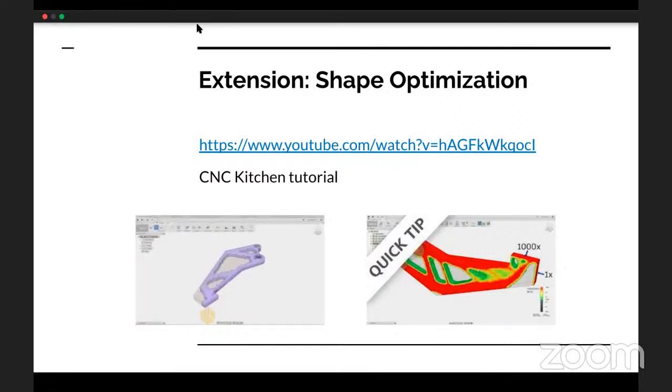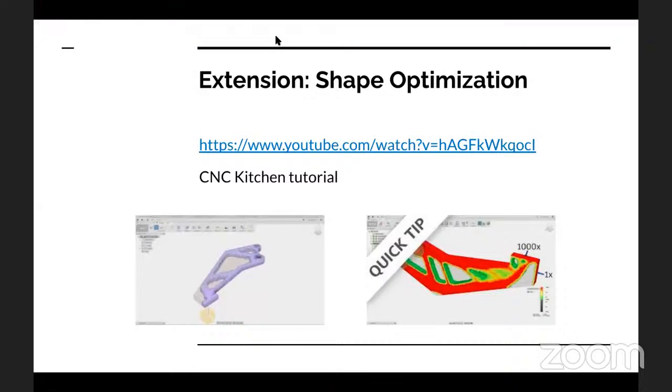So with this last part, it basically can take away unnecessary material, so it doesn't take as long to print, or it's not a waste of material. Yeah, exactly. So we run it through a simulation, and our constraints are like, we want this hole to be kept safe. We don't want the program to alter this hole, and we can also establish a target density, which is how much of the original material we want cut away.